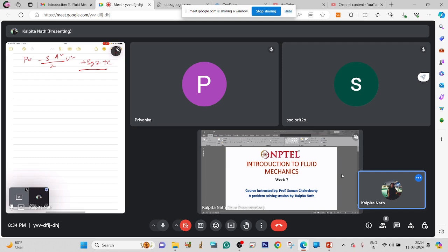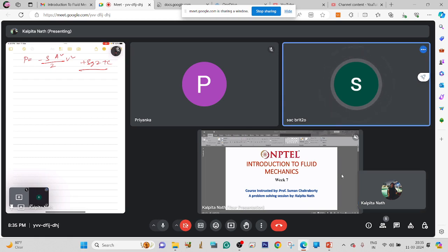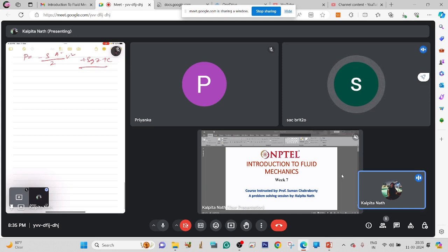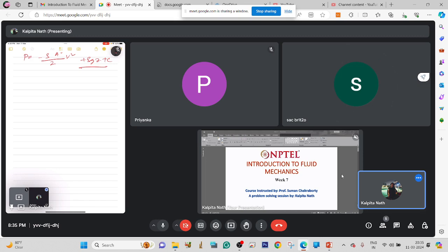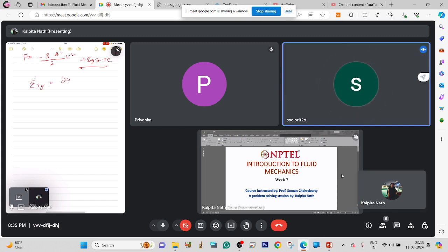Prito, you tell me. Have you attended the previous session? No, ma'am, I haven't attended. Okay, have you taken the classes? Do you know what is shear deformation? Yeah, I have taken. Okay, then the streamline is dx upon u is equal to dy upon v. And the rate of shear deformation is simply xy, which is del u del y plus del v del x. You have already done that in the class, I guess.